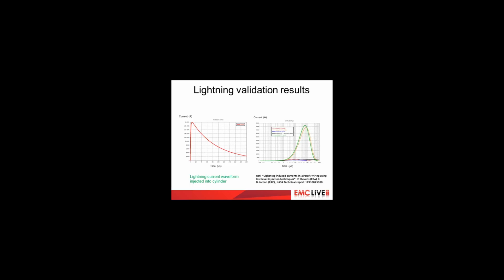Using an aluminum cylinder brings the amplitude down to a few thousand amps, which is the blue and the red results. Finally, if we add wire mesh to the carbon fiber material, the level is reduced from 50,000 amps to similar levels to the aluminum case. We only have a simulation result for this, which is the black curve.